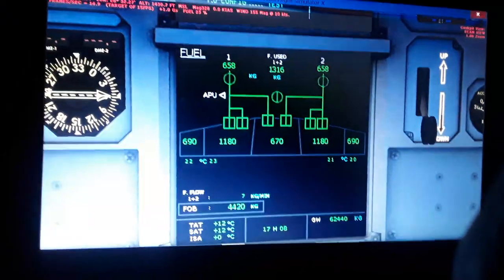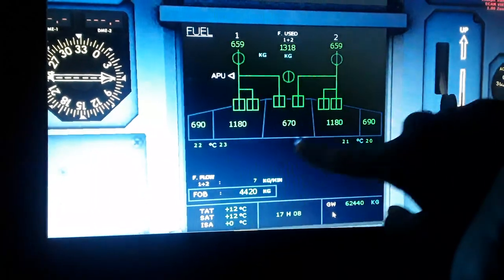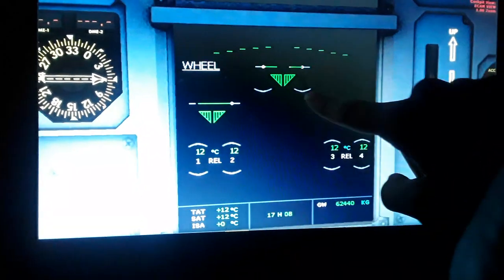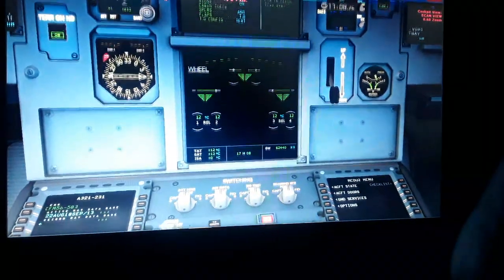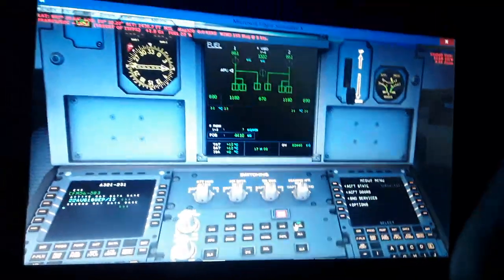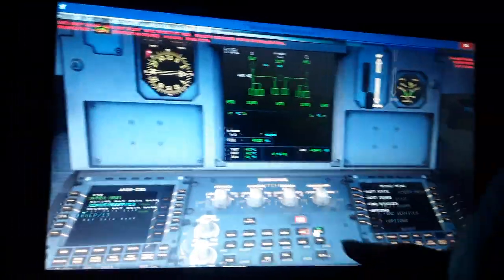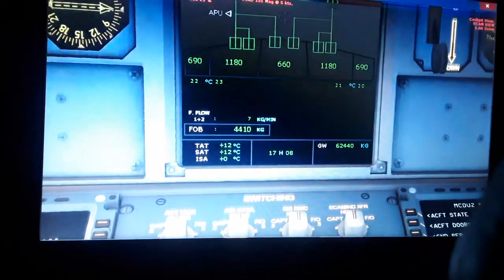So you can see this is the left wing section, this is the right wing, and this is the center of the fuselage. So you can see how much fuel you have in either one. You need the center more for gravity. Also you need the left and the right wing to be balanced within some limits in terms of fuel on board.